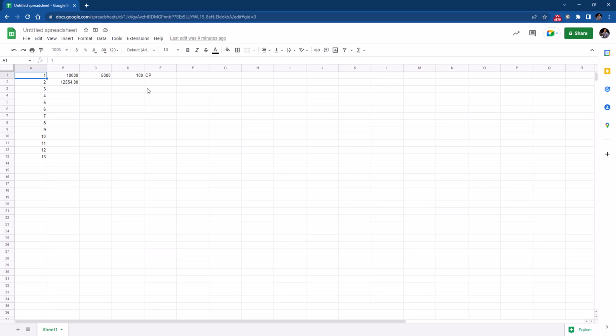in, call it a text file, and that text file is typically used for a survey stakeout in a data collector or a controller, or used to import into a CAD software package like AutoCAD Civil 3D or Trimble Business Center. In this case, like we typically talk about, it uses point number, northing, easting, elevation, and description as a common file format.